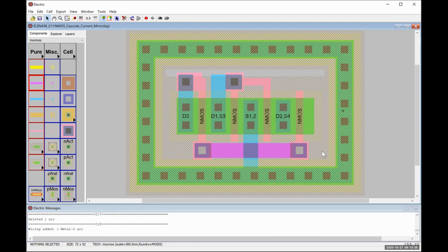and I'm not going to effectively short out those two transistors. I have accidentally formed a small metal 1 to metal 2 capacitor, but let's see, the width of these runs is 4. So 4 lambda would be 1.2 micron by 1.2 micron capacitor. So that parasitic capacitance should be very, very small there. Okay, so that's the bottom portion of our transistor, or our current mirror.